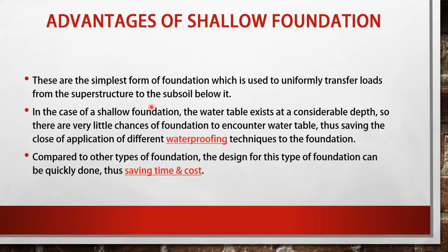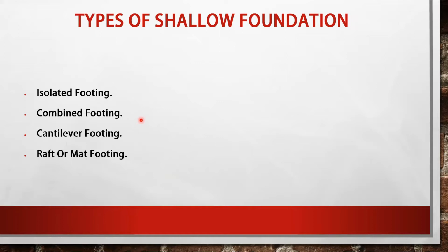Now let's come to the second advantage of the shallow foundation. Since the water table exists at a considerable depth, there are very little chances of the foundation encountering the water table, thus saving the cost of application of different waterproofing techniques to the foundations. While constructing the foundation, we have to use different waterproofing techniques so that the water does not affect the strength of the foundation. Here the water table is considerably low, so we don't need to use any kind of waterproofing technique. Since waterproofing is not needed at a shallow depth, it also saves the time and cost of the project.